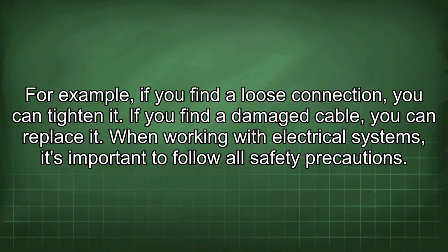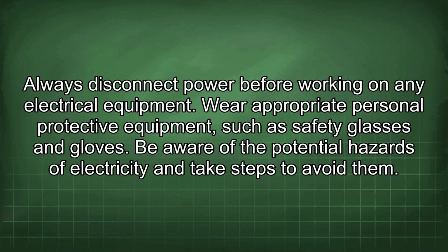For example, if you find a loose connection, you can tighten it. If you find a damaged cable, you can replace it. When working with electrical systems, it's important to follow all safety precautions. Always disconnect power before working on any electrical equipment. Wear appropriate personal protective equipment, such as safety glasses and gloves. Be aware of the potential hazards of electricity and take steps to avoid them.